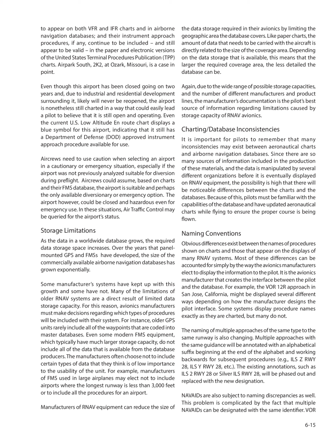Aircrews could assume, based on charts and their FMS database, the airport is suitable and perhaps the only available diversion area or emergency option. The airport, however, could be closed and hazardous even for emergency use. In these situations, air traffic control may be queried for the airport status.